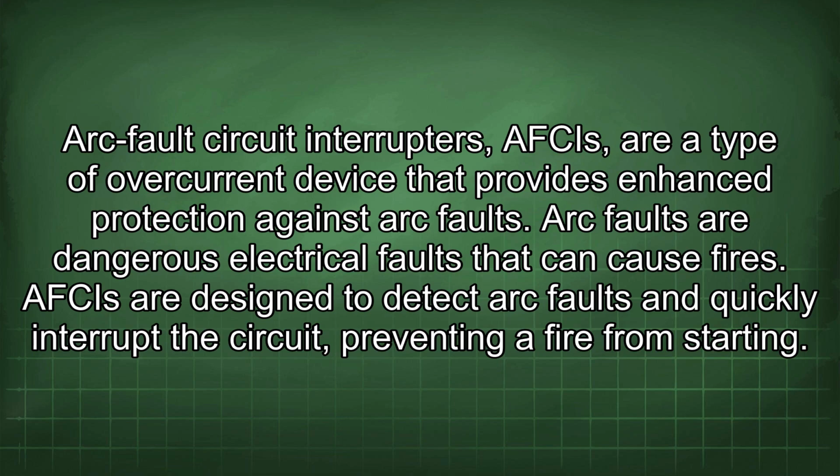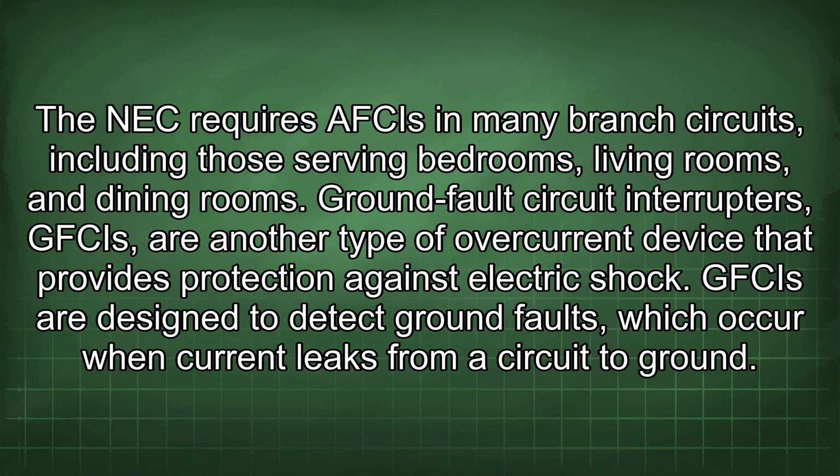Arc fault circuit interrupters, AFCIs, are a type of overcurrent device that provides enhanced protection against arc faults. Arc faults are dangerous electrical faults that can cause fires. AFCIs are designed to detect arc faults and quickly interrupt the circuit, preventing a fire from starting. The NEC requires AFCIs in many branch circuits, including those serving bedrooms, living rooms, and dining rooms.